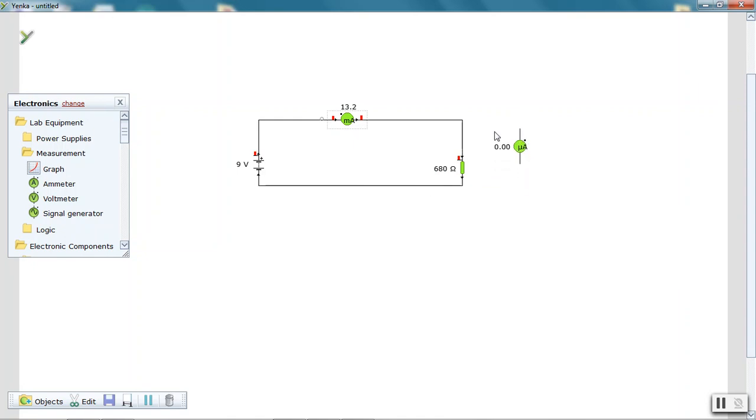The other arrangement would be what's called a parallel arrangement. We hook one end of the meter on one side of the resistor, and the other end of the meter on the other side of the resistor. When I make this connection, there will now be 2 paths. The path splits. The path is going to split here. There'll be one path this way and another path this way through the meter to this point after I make the connection. So that's called a parallel arrangement where you have 2 paths. So let's hook this up here.